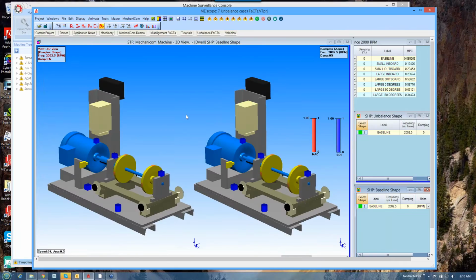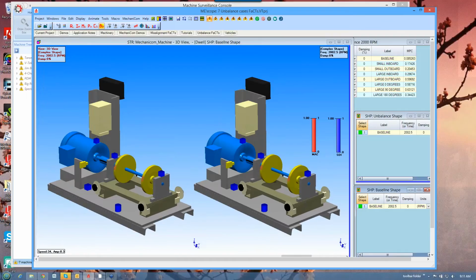It's important in ODS when we're comparing vibration data. Let's say in this case the running speed of the machine, the first order, when we're comparing operating deflection shapes, we want to compare magnitudes as well as shapes. So let's just walk through some of these cases. Now I've got some hotkeys up here. The first one says balanced. So that's the case we're looking at right now. If I push that button, Scope shows me the two shapes, and left and right are balanced.